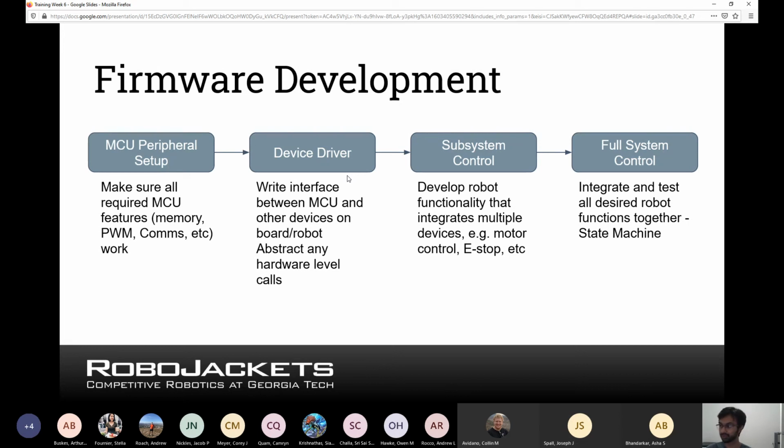Some of you may remember from firmware training, we had to set some bits directly in order to make some actions happen on the IMU. But an alternative to that would have been to write nice calls and methods that wrap around that bit setting action. And in doing so, you make it easier for everyone to write code because they don't have to go back to the datasheet and check, oh, I needed to set bit number 3. Instead, they just have a method which automatically does it.